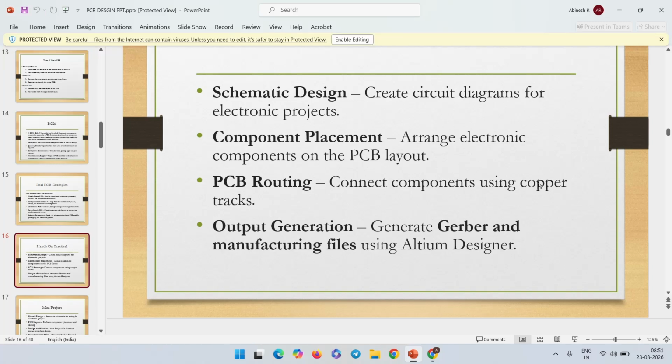Okay, if you have any error, then go through the error and find where it is being caused, which means a spacing or clearance between one component and another component, or spacing between the traces, or any other complexity you are facing, and you can overcome that. Okay, these are the main functions of a design rule check. Once the design rule check comes to zero, then you have no error in the PCB.